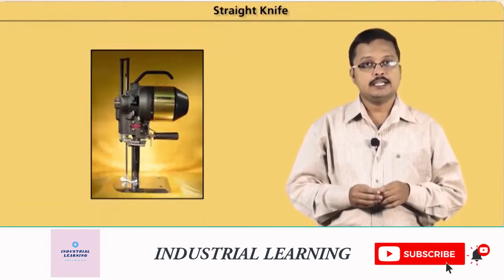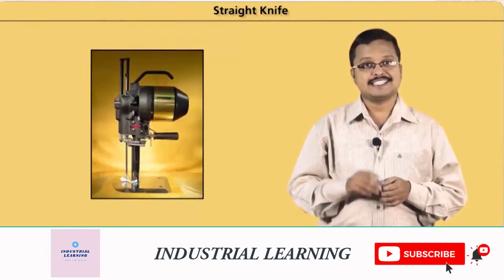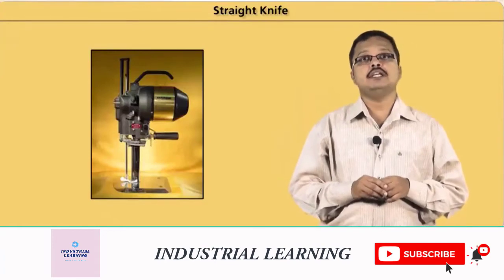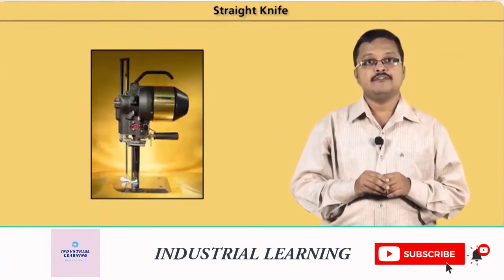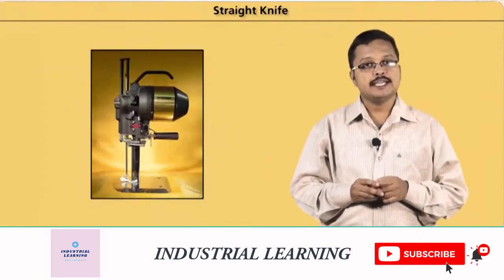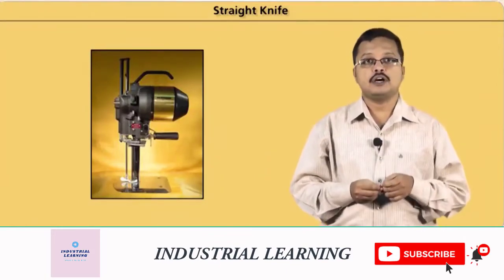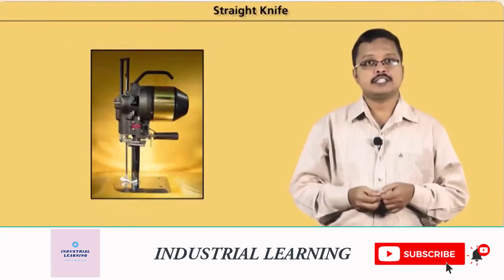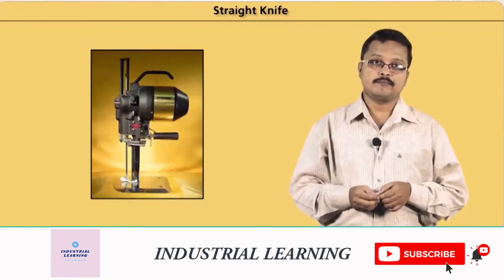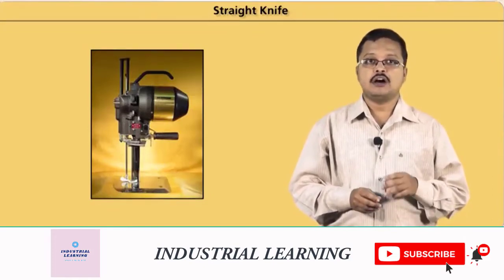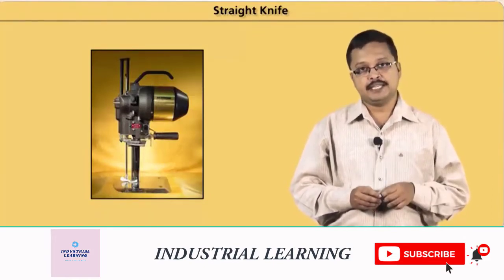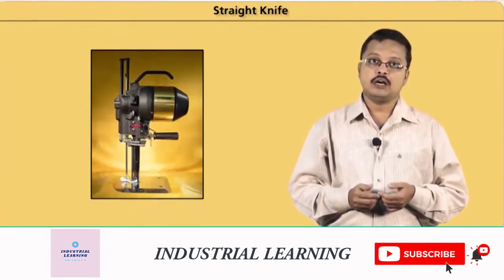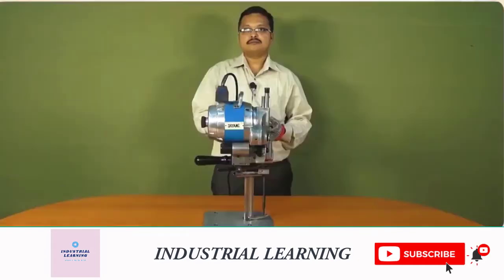The cutting blade is available in various edges such as straight, serrated and wavy edge. The most commonly used is the straight edge. Wavy edges help to reduce heat generation and are used for cutting plastics and vinyls, whereas saw edge types are used to cut canvas. The straight knife is also available in varying speeds, allowing the same machine to be used for natural or thermoplastic fabrics.